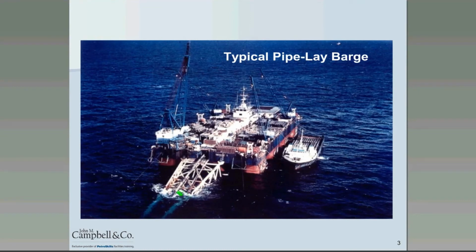Now, again, if you look closely, you can see down in the water that this piece of equipment does transition from being in air to underwater, and you can also see located there supports that provide support to the pipe, and these are roller type assemblies that help in the transition. Okay, so a lay barge. This is the lay barge where the assembly is done. This is the stinger truss configuration to help the transition, and of course then we have the object of all this activity, the construction of the pipeline itself.